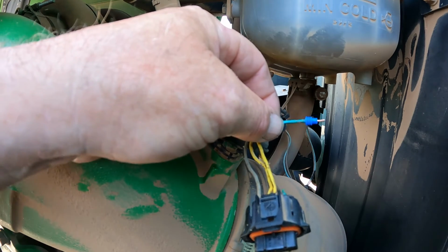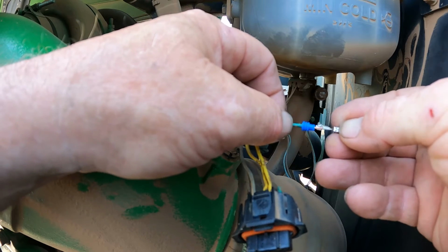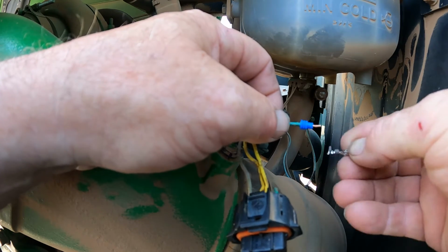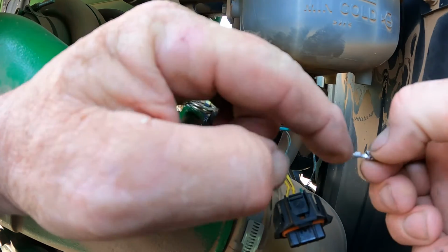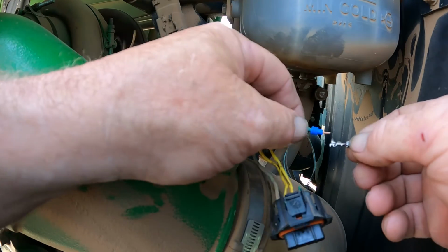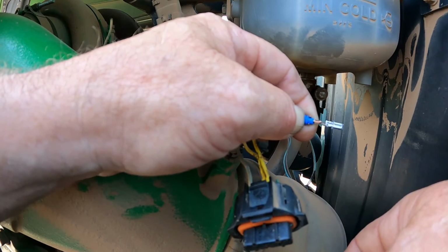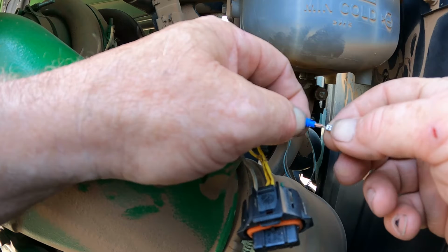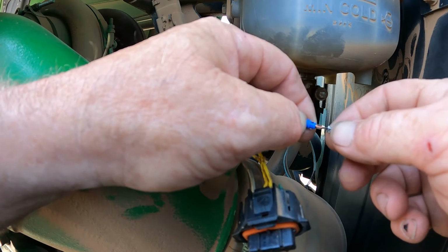And then I've got a crimping tool here that I like to use. So if you're looking at the terminal, the back portion of the terminal will bite down on the seal, and then the middle of the terminal will actually be what you will crimp to the wire, okay? Sort of like that. Okay, so keep that in mind if you're installing one of these, to make sure you get a good crimp on that, okay?